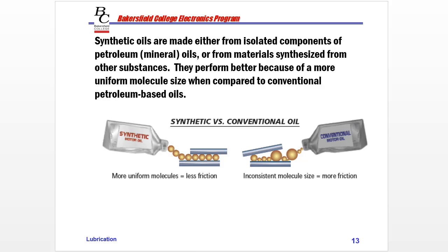It is fully compatible. What you're going to get with synthetic oil is a longer lasting oil, because we're not breaking down the oil as fast because the molecules are the same size. Here we're going to break down these larger molecules, and the oil is going to break down. So then it's going to have less of an ability to coat the metal products properly. And the oil is going to get dirtier faster and will need to be replaced sooner.